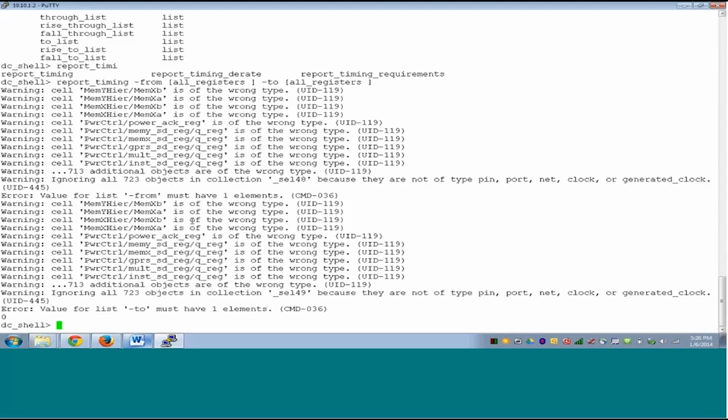So a lot of things we'll see will start working in PrimeTime that are not working here. I have to write a procedure to report register to register path. That is why it's very useful to create groups from the starting. We'll see that in the next lab perhaps. Now we saw how to report the worst path. We saw how to report from and to.